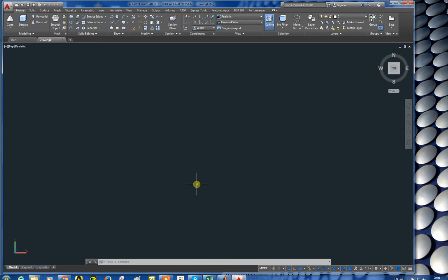Part of this presentation would be introducing 3D modeling using four basic tools. We have the extrude, we have the loft, we have the revolve, and we have the sweep. So we're going to be using those four tools one after the other to introduce to us what we mean by 3D modeling, just in case we're not interested in using the already predefined solid geometries.